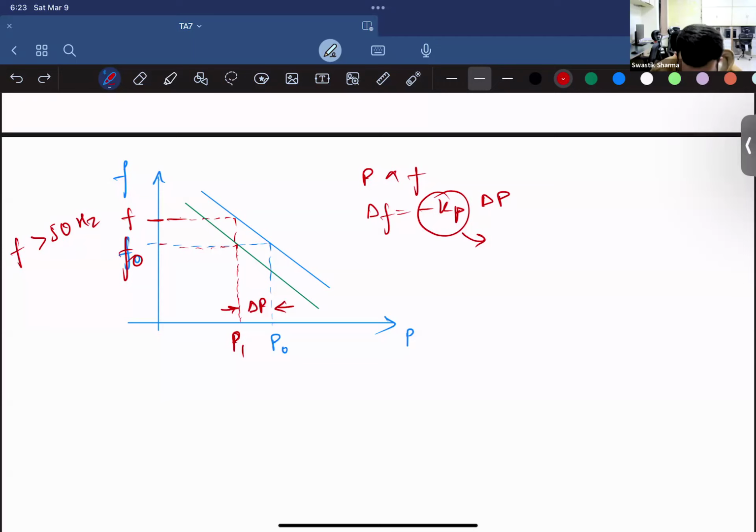Okay, so that's how they do it. But generally, what we do is we have multiple generators working in parallel. So we add one more generator, or we change the KP values in such a way that both the generators match to operate at a normalized frequency of operation.